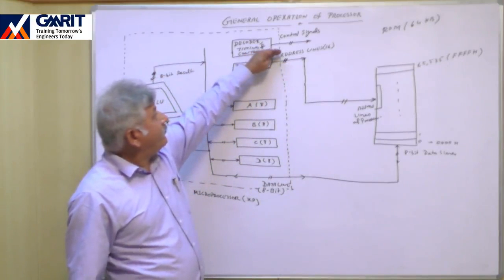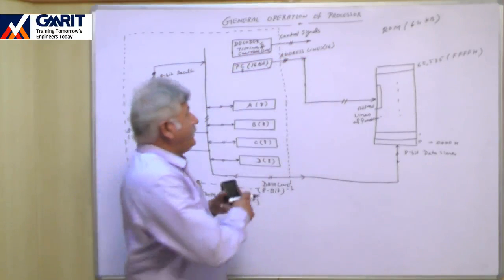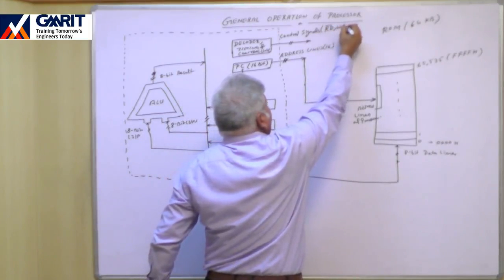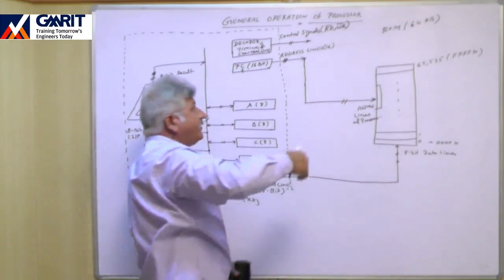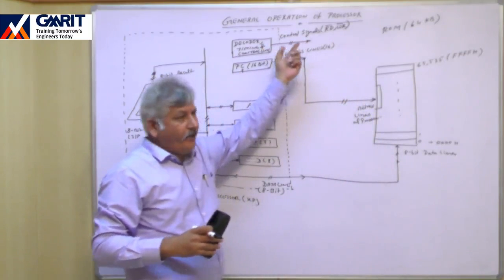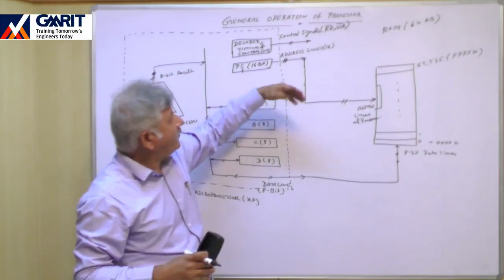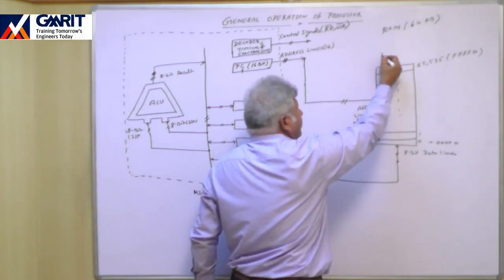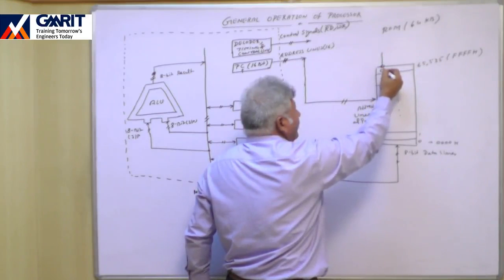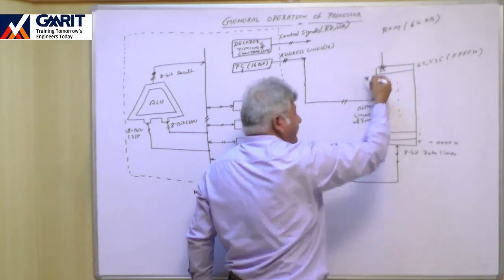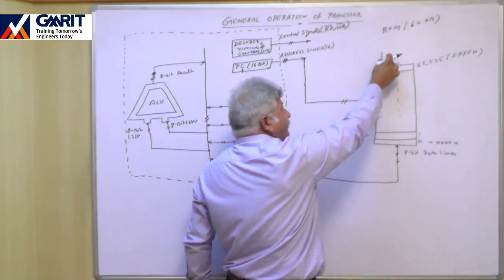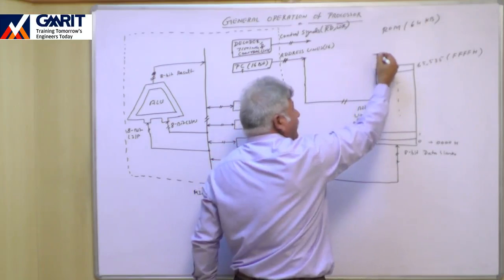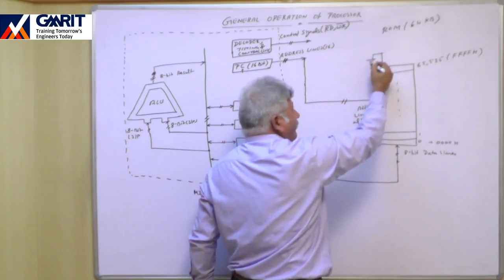And this timing and control unit will generate control signals like read bar, write bar, and some other signals are also generated by the timing and control unit, but we will take those signals in coming lectures. Now since this is a ROM, here we have CS bar, chip select. To select this memory, this pin must receive binary 0. So I will connect this to ground.